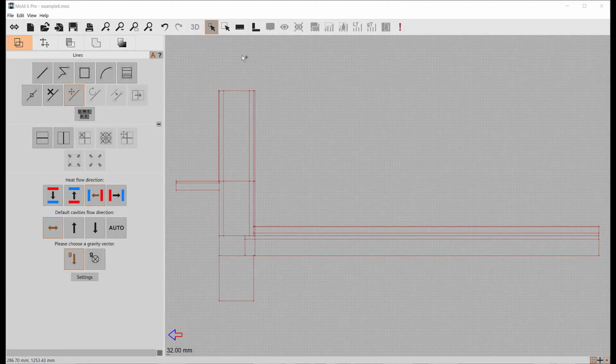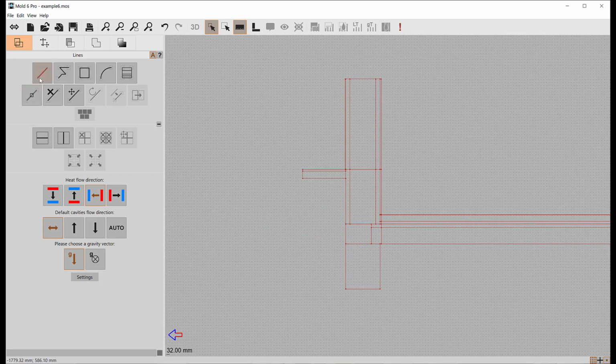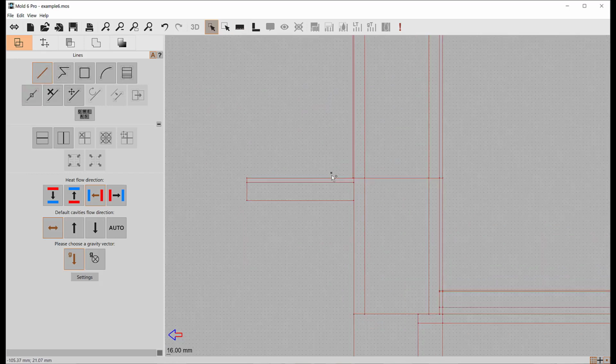We start from a previously saved geometry with all the materials assigned. The characteristic width of the floor B is 8 m, so the width of the floor is 4 m. According to ISO 10211, we need a ground with a size 2.5 times the width, which equals 20 m.